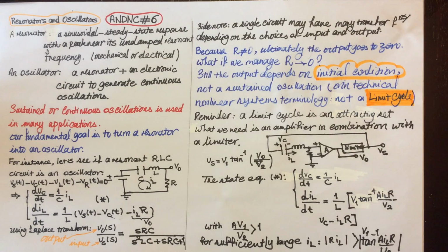We're particularly talking about, for example, in modern applications, MEMS devices, and many MEMS devices are used to generate these limit cycles for various applications. For example, if you think about the Coriolis gyroscope, the way it works is from basic applied mechanics. We know that we have this Coriolis force, which is 2 omega cross V, and the V in gyroscopes is the velocity in the drive direction, which generates a response in the sense direction. So we do need to have sustained oscillations just so that we can use this Coriolis gyroscope to measure angular rate.